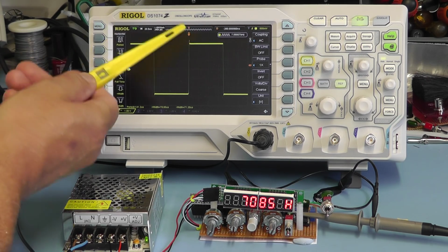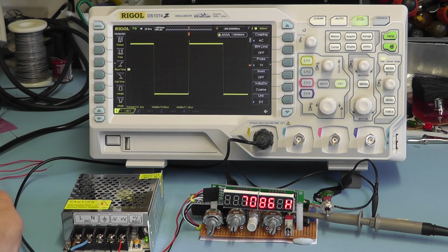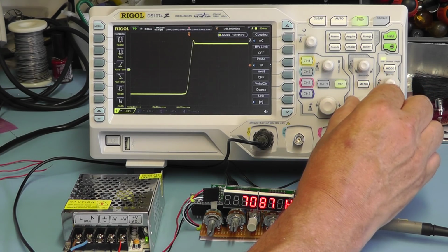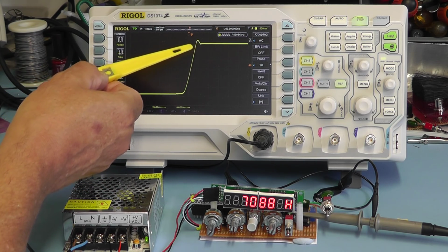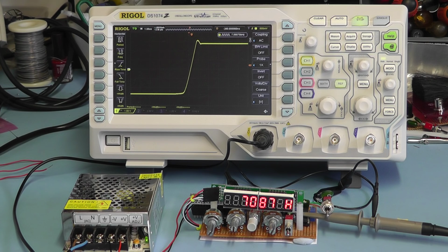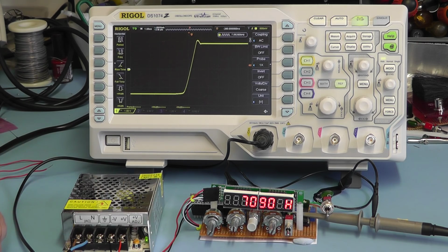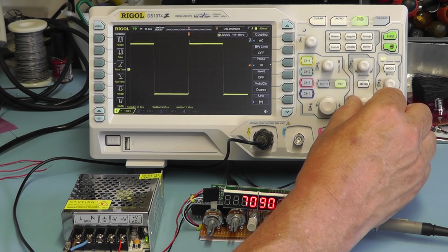As you can see on the oscilloscope, we have a little bit of overshoot there on the square wave on the leading edge. I'll just expand the ring on this, and you can see that slight overshoot. We could probably get rid of that by adding a small value capacitor in the feedback loop on the operational amplifier in the output stage there. So I'll come back to that and we can see whether we can improve on that. But really that's quite a minor issue.